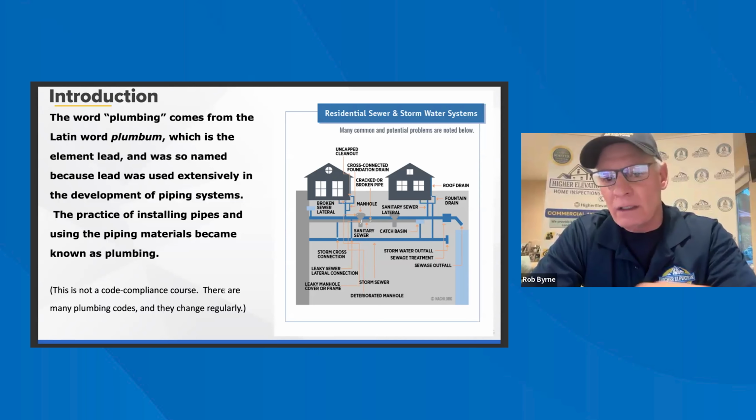These are some of the defects that we look at when we're checking for the water heater part of the inspection. Check for physical damage to the tank, particularly rust and corrosion on the bottom of the tank. Check for watermarks on the floor. Obviously, if the tank's leaking, you'll see it. Inspect the TPR valve, which we just spoke about.